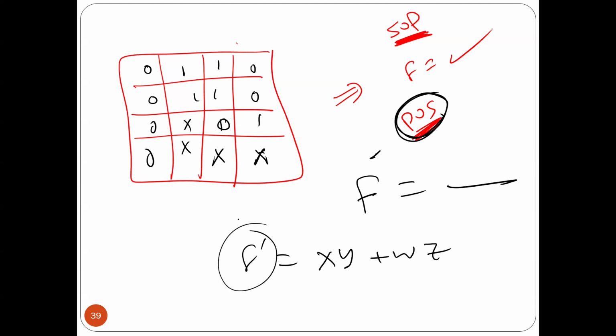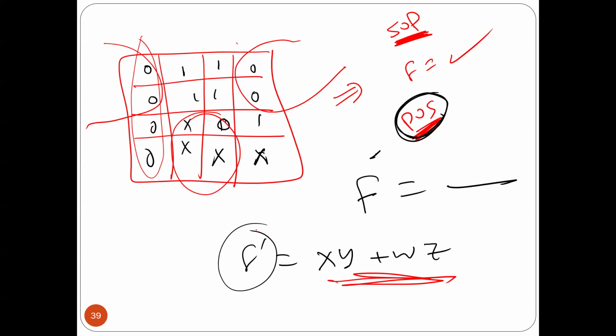So now if I group zeros, for example, in this example here, yeah, I can take these zeros together. Okay. And then I can take these 4 zeros together. Okay. Then I can take these 4 zeros here, this is one solution to do it. So now I will get whatever you have here, but it's going to be F prime. F prime is sum of product. And then after that, if you take De Morgan of this one, in order to get F, F is equal to XY or WZ prime after the De Morgan. And now it becomes...